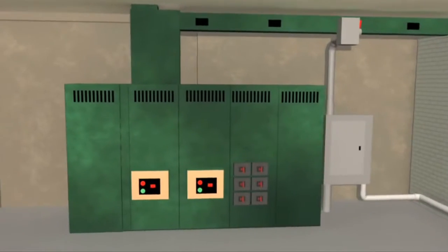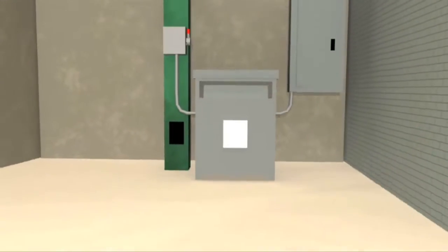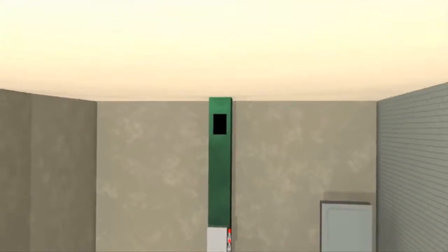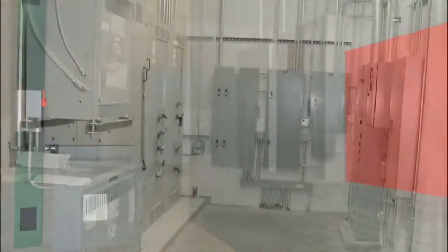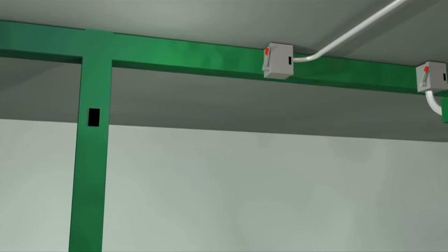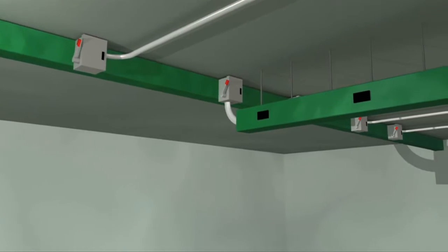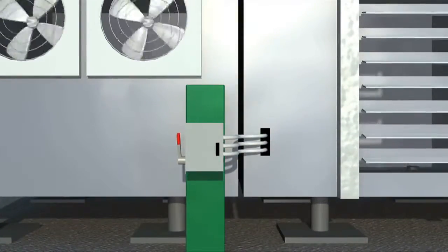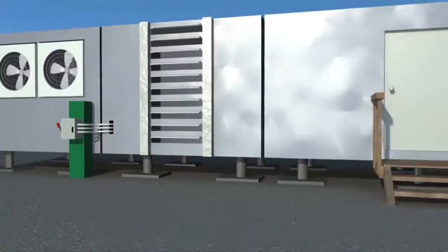In our example facility, you see the bus duct rising vertically to the roof. It passes through an electrical room on each floor. These rooms generally house breaker panels, 1 or more transformers, and/or disconnect switches. Power is then distributed throughout the floor. The bus duct reaches the roof to supply power to HVAC systems through a disconnect.